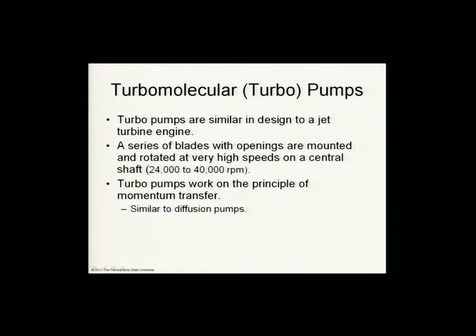So turbomolecular pumps, affectionately known as turbos, are a lot similar to a jet engine. You know how a jet engine transfers momentum to the air molecules at atmospheric pressure, or maybe a little bit below atmospheric pressure, but at 37,000 feet, definitely below atmospheric pressure. Because when we say atmospheric pressure, we're talking about at sea level. But like a jet engine, it transfers momentum to the particles and then shoots them out the back end. So that's essentially how a turbo pump works.